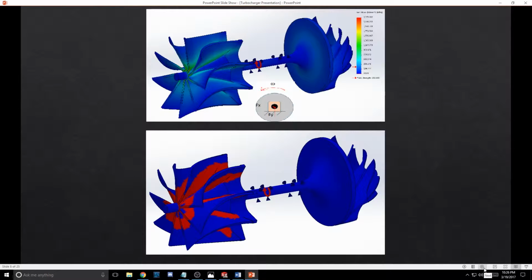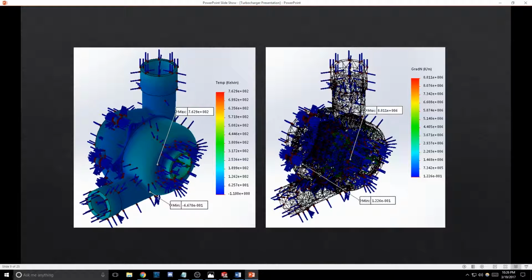Not only are we concerned with the thermal effects, but also the force exerted on the inner wall of the turbine housing in order to calculate the stress on the flange of the housing, as it is the only rigid connection of the assembly to the car engine.